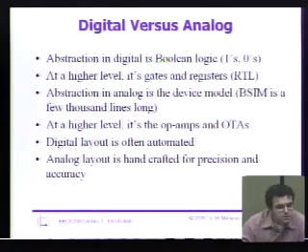Also, the parasitics are huge, very important, right? So when you do analog layout, if you lay things out in a stupid way and you put one transistor really far away from the transistor that's driving it, you're going to end up with all this parasitic, and it's going to really impact the performance of your circuit. And those parasitics, you can estimate them now in an automated way, so that you can extract capacitance and resistance, maybe even inductance for really high-speed applications. But the extractions are not very accurate. Their accuracy is on the order of 20–30%.